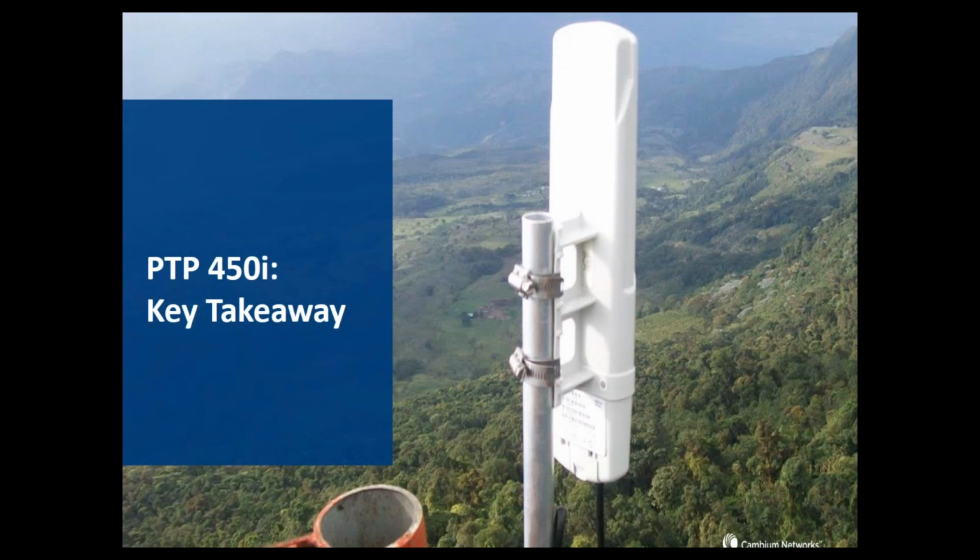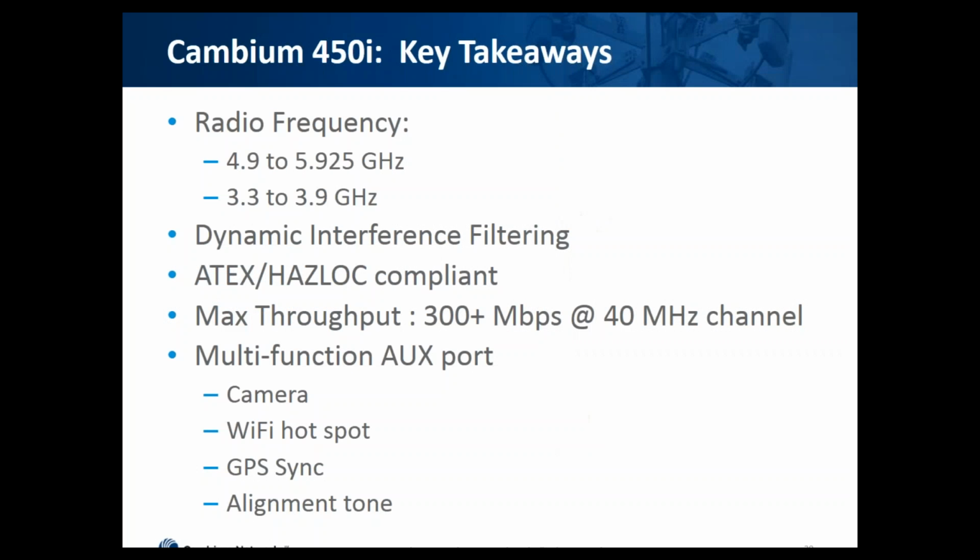All right, now we're going to do a quick takeaway of the high-level points of the PTP 450i. The first one, the radio: there are two versions of the PTP 450i, the 5 gig band and the 3 gig band. The 5 gig band works in the 4.9 to 5.9 range, and the 3 gig is from 3.3 to 3.9. One of the key feature highlights is dynamic interference filtering for the PTP 450i. We also have ATEX and HAZLOC compliant versions of the PTP 450i already available. The max throughput for the 5 gig is more than 300 Mbps at the 40 MHz channel.